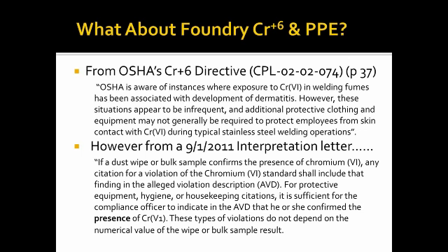So I've put two things in here, and the reason I have both of these is they're kind of contradictory, and I haven't figured out how OSHA would approach this. But in their directive, and this is also in the preamble to the standard, they recognize that welding, and I would throw in the pouring and melting operations, because it's a very similar situation to welding, is that these things really don't cause dermatitis, that it's infrequent, and that there is not specific PPE required for hex chrome during these operations.